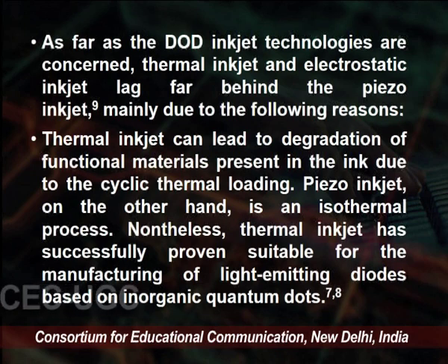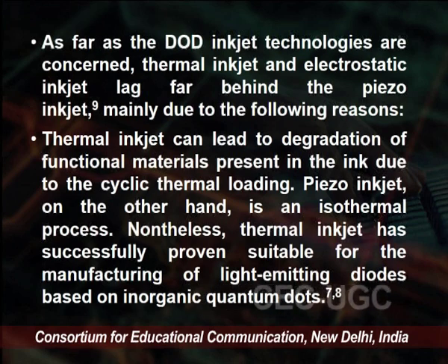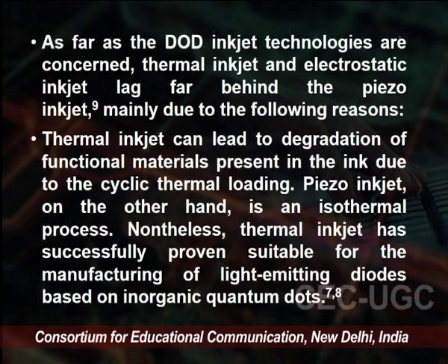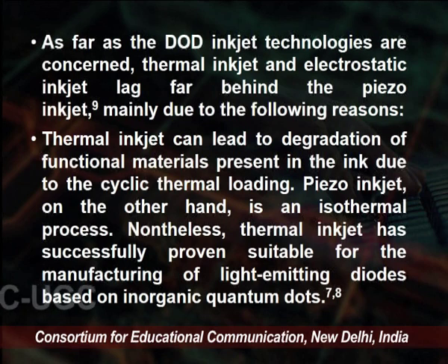If we talk about drop on demand inkjet technology, thermal and electrostatic inkjet lag far behind piezo inkjet, mainly due to the following reason. Thermal inkjet can lead to degradation of the functional material present in the ink due to cyclic thermal loading. Piezo inkjet, on the other hand, is an isothermal process.